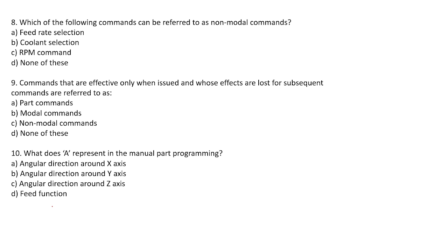In the case of non-modal commands, they do not remain active or in effect after they have been executed somewhere in your part program. They only affect the next line of that NC program.